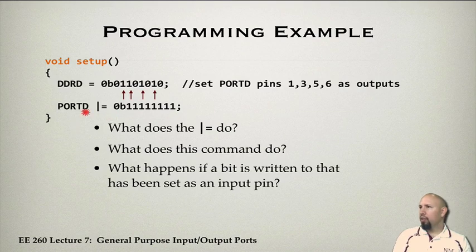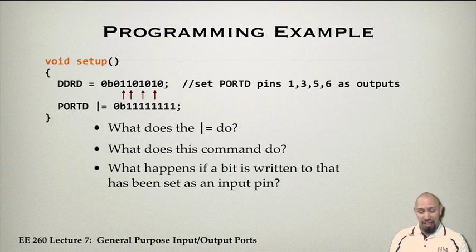Basically here we're setting some of these pins to be pull-up pins. We weren't asked to do this, but that's what would happen if we did this. All the input pins would have pull-up resistors with them. Well, that's the setup program, and actually I threw in more than was needed, which can be very dangerous.